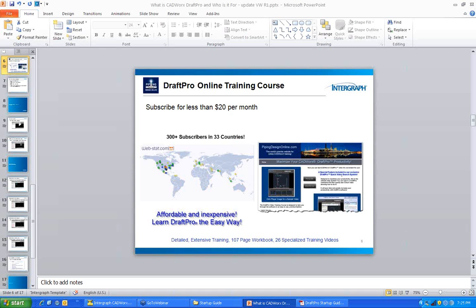users, and we've made it available free. So when you're using CADWorx DraftPro, you can either draw in double line or you can draw in single line, but it is not a 3D model. Okay, and so what we've done is we have disabled that function. So if you do want to use a Caesar 2 output, then you would have to create a CADWorx Plant Professional file. And if you're going to be a house that's going to be using DraftPro, then what you would want to do is consider using CADWorx Plant Professional instead.